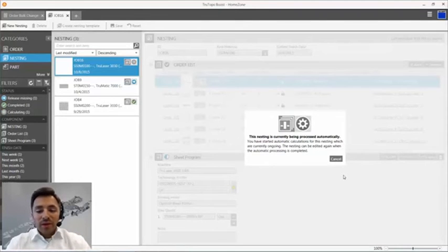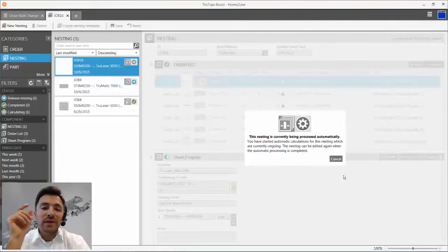So right now in the background, of course, the sheet is being taken. Nesting mode is optimal sheet format. So the technology is applied for all the orders within the order list, and we even generate, of course, the NC. And basically for the nesting, you can preset a certain nesting profile, considering the part distance, the sheet margin, and the nesting algorithms themselves.